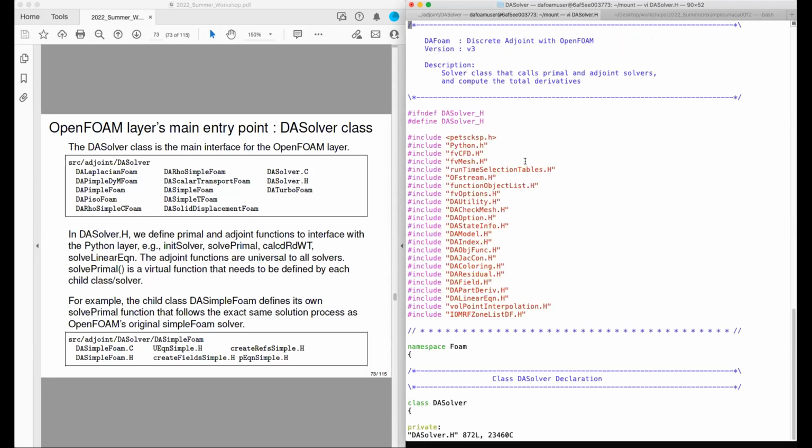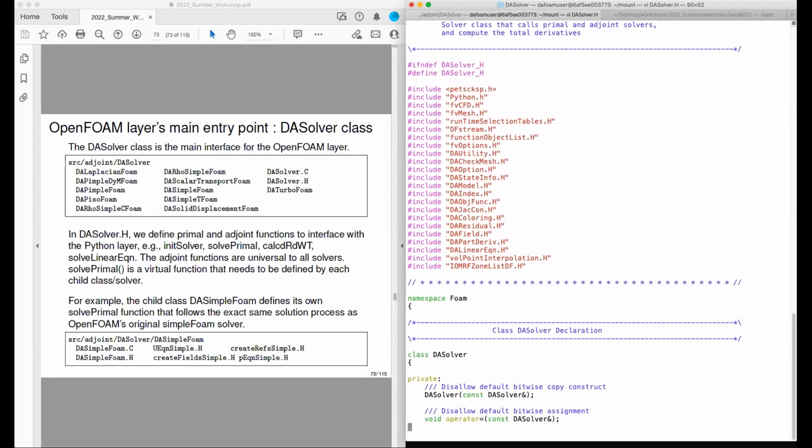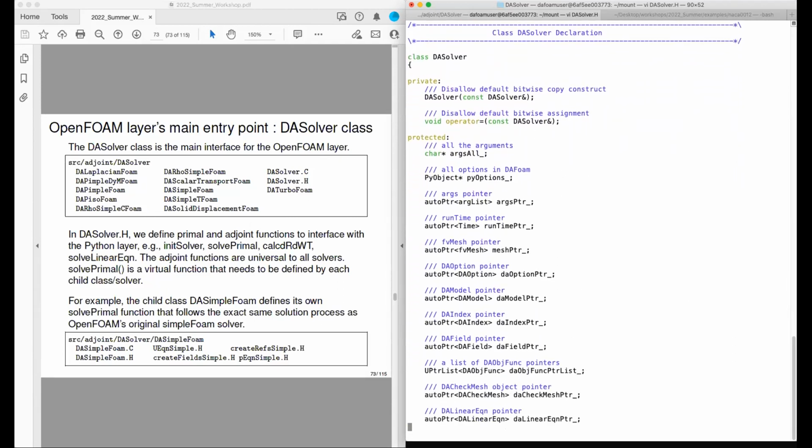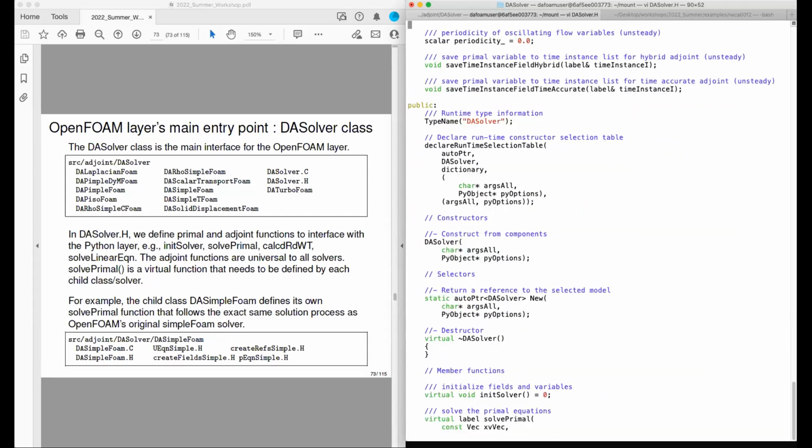So this is the main entry point, meaning that the Python layer can only call functions in this file. If your function is in a different class, the Python layer won't be able to call it. So if you want to expose a function that is callable from the Python, you have to write the class, write the function right here in this DASolver.h. I'm going to move down. You can see that, for example, I'm going to search for...